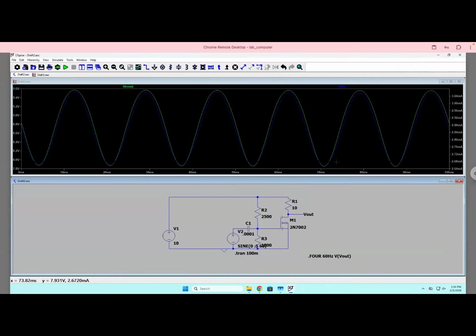The higher that percentage is, the less sinusoidal it is; the lower that percentage is, the more sinusoidal it is. If you're doing digital devices and you have switching noise on it, that'll increase your total harmonic distortion percentage. If you're doing analog stuff, it basically just changes the shape instead of adding a little bit of wiggle to it. Yeah, that's kind of the majority of project 2.